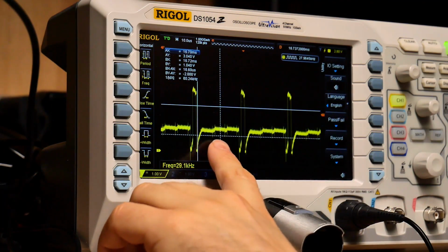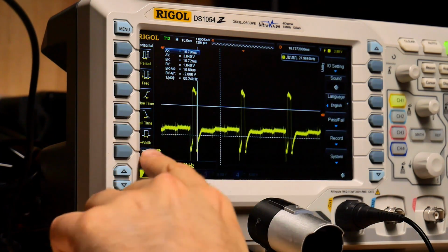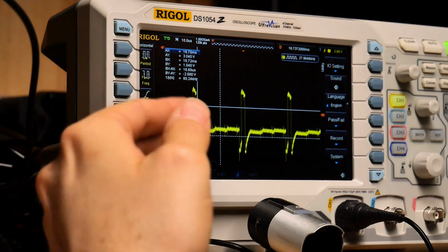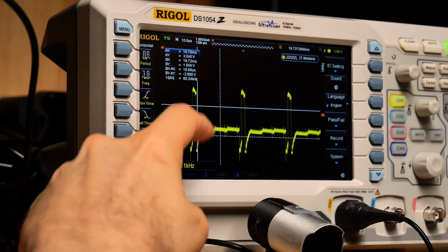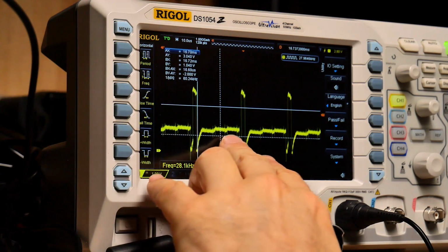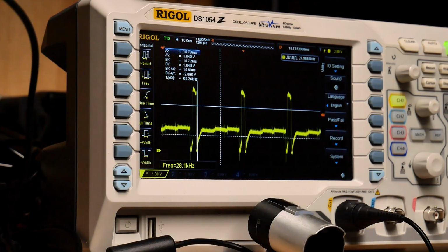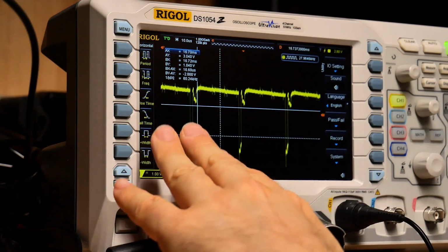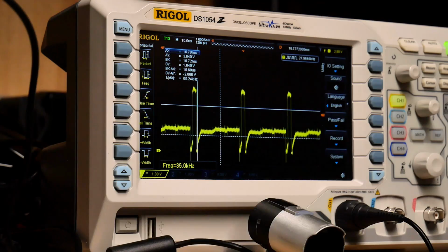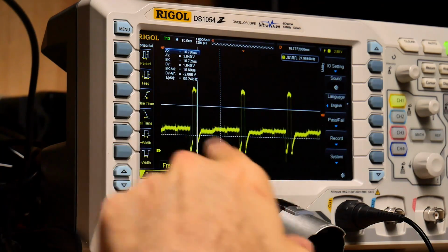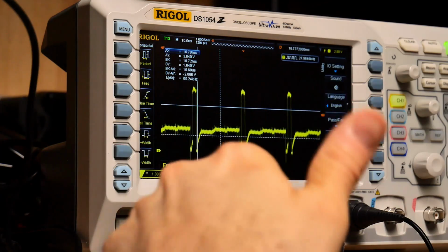Now this looks a bit strange. What's going on here? Now this could easily be because the data line is floating, like nothing's connected to it. And we do see a high and we do see a low, and that seems fine. So I'm thinking this is a tri-state bus and this is just floating. So that's not that big a deal. This one looks fine. This one looks okay. Here's another one where it's sort of stuck in the middle. Now it's weird how not everyone is doing that. So I'm wondering if this actually indicates a fault.